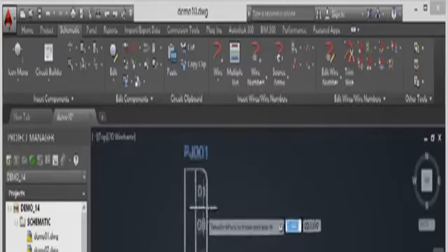So if you want these all to be nice and equally spaced, maybe pop a few little construction lines in there that are nice and neat and space the numbers out neatly and tidily, and maybe use the object snap to snap to on the connector using an endpoint or intersection snap maybe. Now you'll notice as soon as I do that, the next available pin on the command line is now 06.